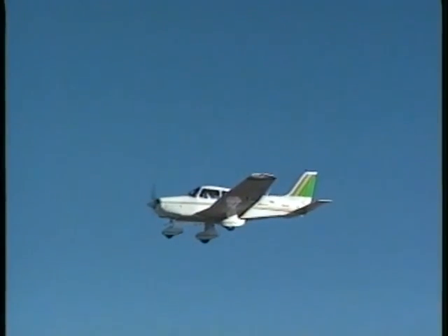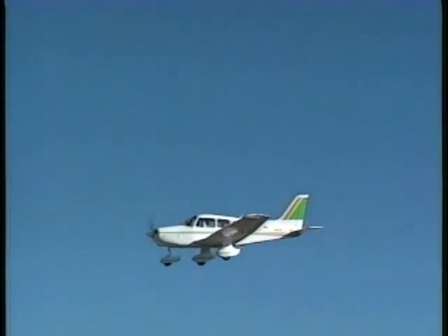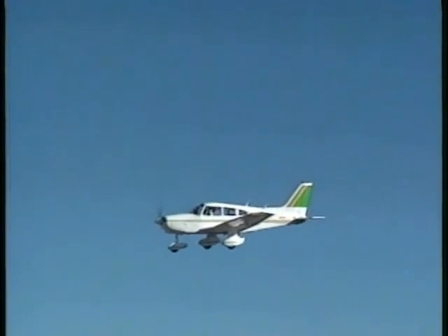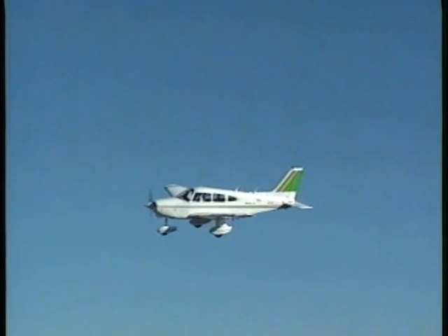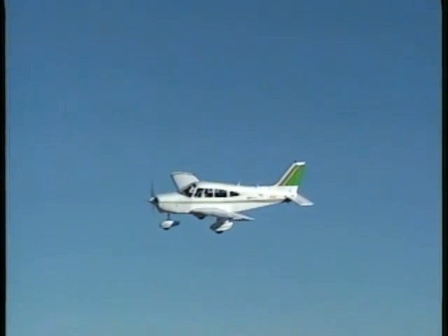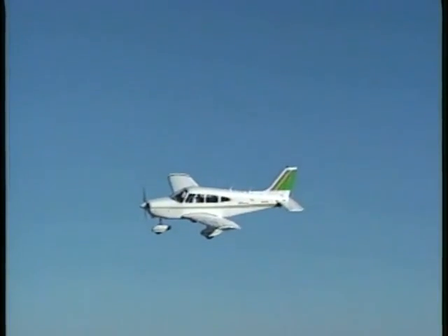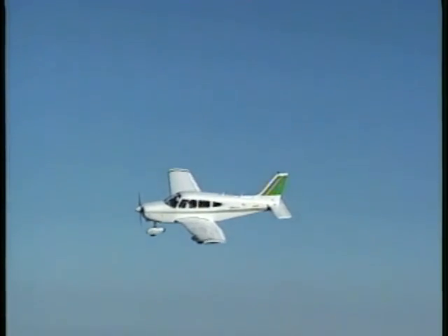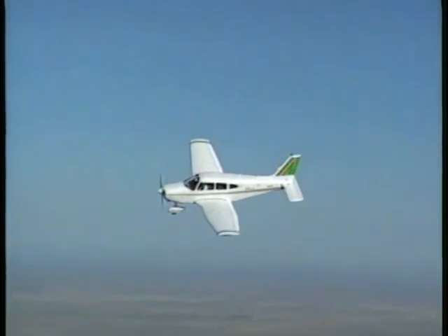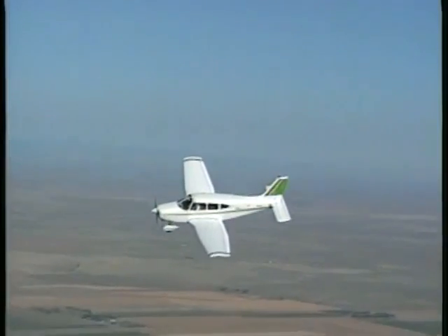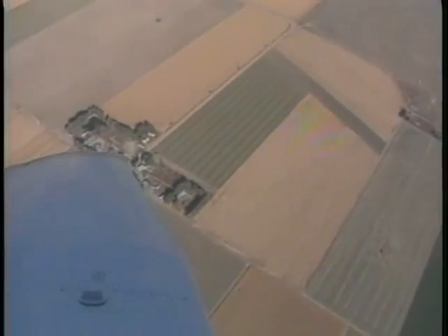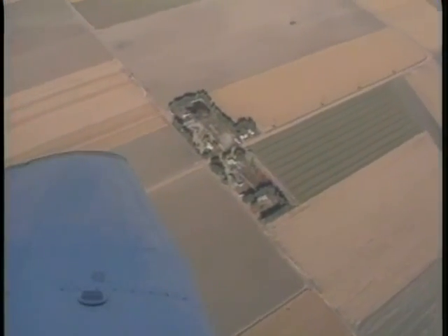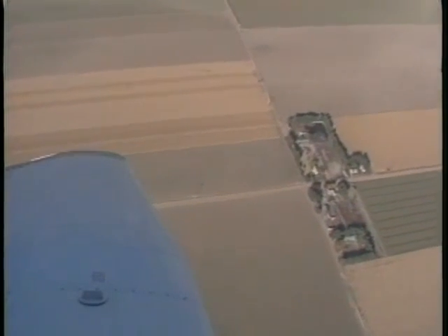One practical application of the steep spiral is during an emergency landing. If you lose power and have sufficient altitude, you can glide directly to your point of intended landing and then lose altitude by performing a steep spiral until you roll out on the downwind leg. As you're descending, you can inspect the site for obstructions or hazards. You can also determine the approximate wind direction and velocity.